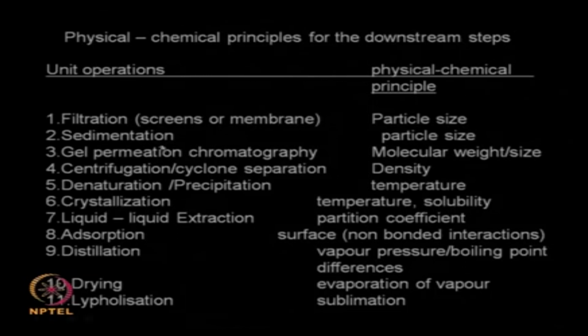Same thing with sedimentation. What is sedimentation? We are trying to settle large solids in a slurry. So, again it is based on particle size, agreed. So, if you have large particles and the liquid is stationary, the large particles will settle down and the very small fine particles may not settle down.